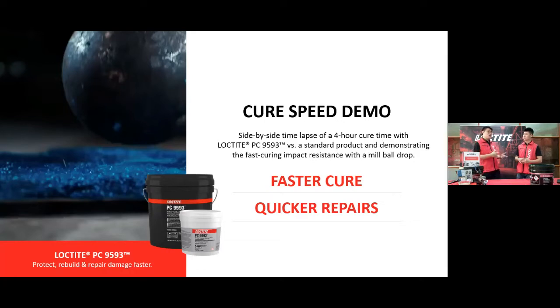So Kim, since you showed the video that our product has 4 hours fast curing, how about the typical other Loctite products, and also compared with the general market impact resistant products, what is the curing time difference? Okay, if you remember, a couple of slides ago, the 7218 and 7226 have curing times of about 6 hours. So this 9593 has even faster curing times, around 3 to 4 hours. And what I understand in the market is that our competitors or other brands have curing times ranging from 9 to 12 hours. Some of them even take 24 hours to get a functional cure. All right, thanks Kim for this sharing.